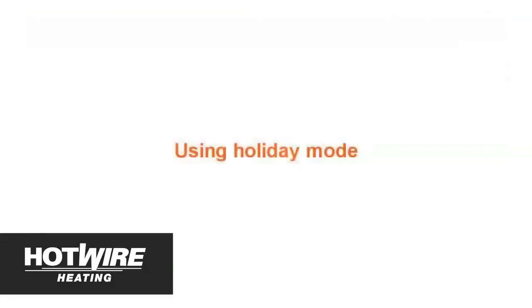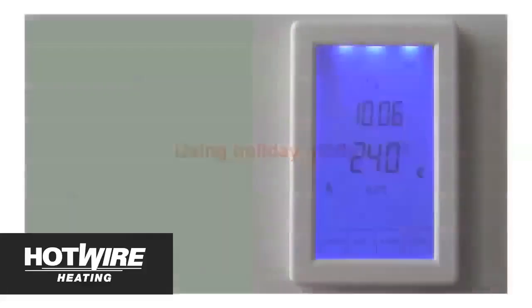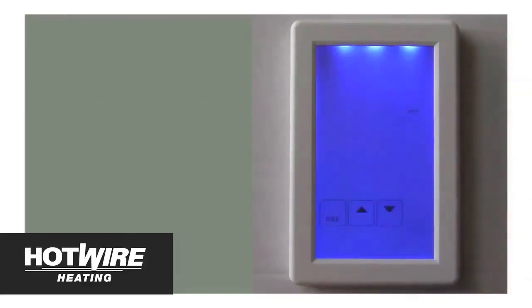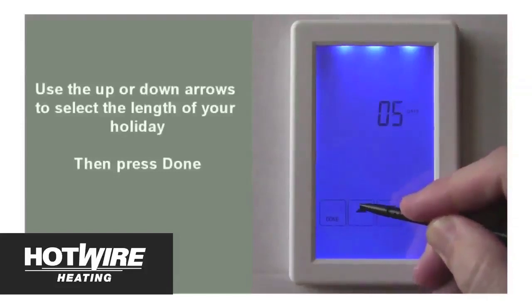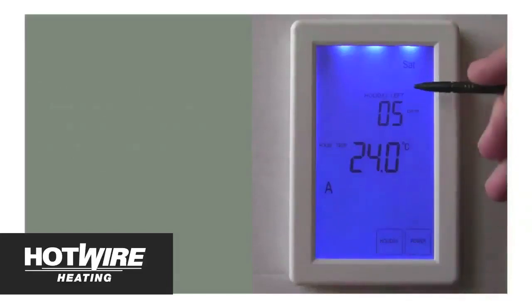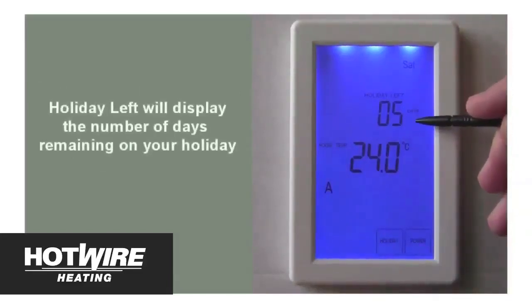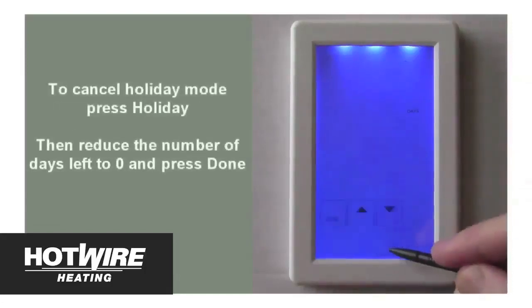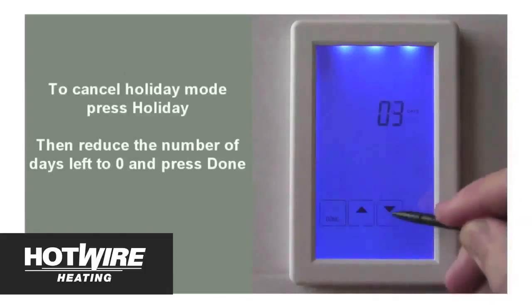Using Holiday Mode. Holiday mode means the unit will turn off for up to 99 days, only turning on if the temperature falls low enough to activate frost protection if you have frost protection turned on. To put the unit in holiday mode, press the Holiday button, select the number of days you'll be away, in this case 5, and press Done. The unit is now in holiday mode and will display the number of days remaining at the top of the display. To turn off holiday mode early, press Holiday, adjust the number of days back down to 0, and press Done.